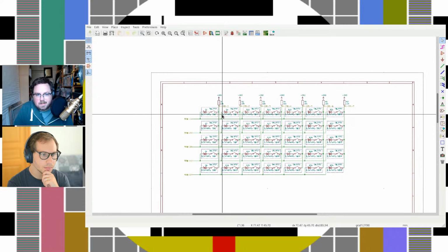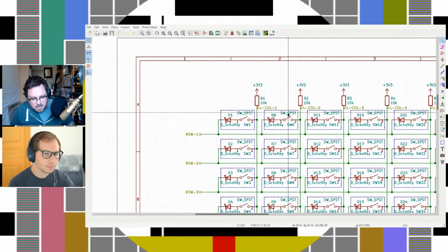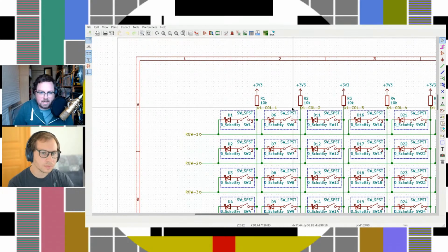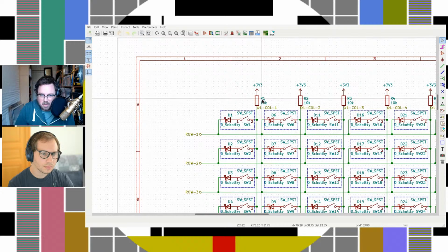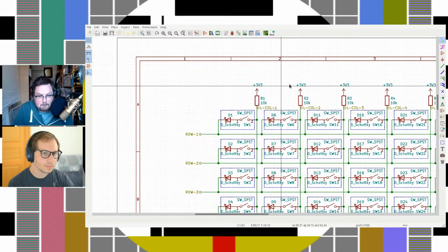But mostly, you can look up this circuit and find out those values, and there's typically ways to calculate what a reasonable value is. For cases where you're pulling this value up weakly just in case things don't go as planned, there's certain numbers, like anywhere from 1 kilo ohm to 10 kilo ohms, that will likely be good. When you look at this design, someone might note that this is a pull-up resistor. You can look up what a valid value is for that, and then measure how long it would take to do things like that.